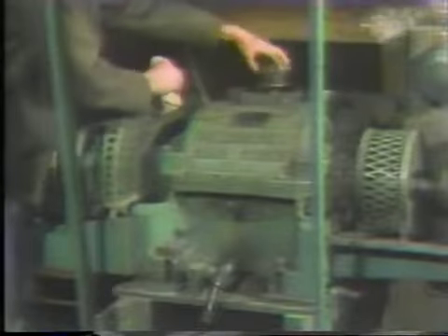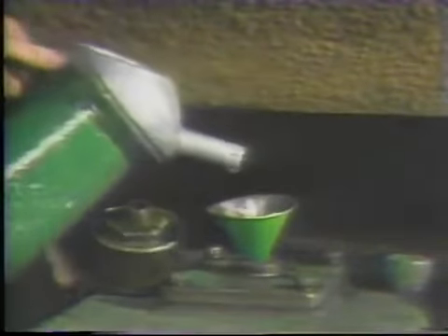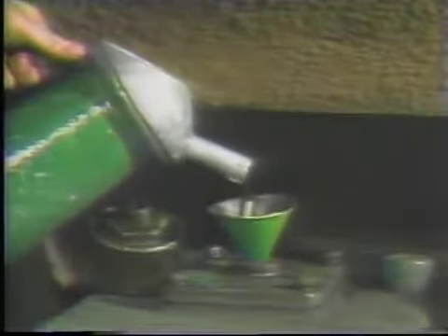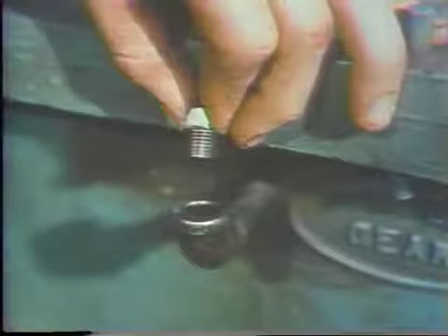If oil is needed, the operator removes the fill hole plug from the top of the bearing and pours oil into the hole until oil reaches the spill hole. An oil level at the spill hole tells the operator that the reservoir is full. Next, he should replace the spill hole and the fill hole plugs.